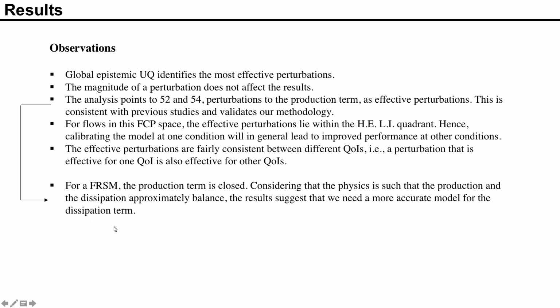Now for FRSM, the production term is closed. So perturbing the production term does not make too much sense. Nonetheless, considering that the physics is such that the production term and the dissipation term approximately balance, the results here suggest that we need a more accurate model for the dissipation term. Let's see whether that's the case.